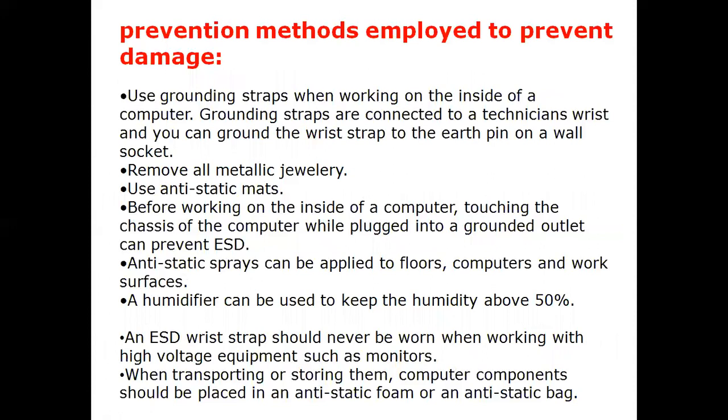Prevention methods used to prevent damage: use a grounding strap when working on the inside of a computer. Grounding straps are connected to the technician's wrist. We can use an anti-electrostatic wrist strap. You can ground the wrist strap to the earth pin on a wall socket.